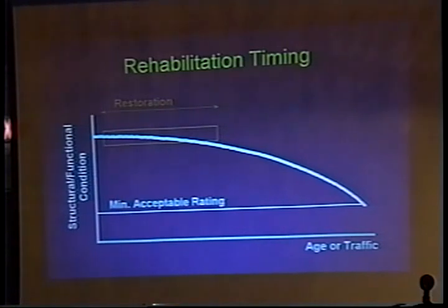If you're starting to see some faulting in your joints, maybe some slab movement because you've lost some support underneath with the subgrade, pumping, whatever, you might use slab stabilization methods, pumping grout in there. This area again, like I said, after these methods, right at that point, you really need to restore the structural plus the functional ability of the pavement to accommodate the loads and the users and what they expect out there. You might take a look at a bonded concrete overlay up in this area.